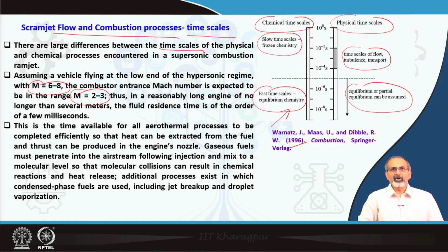Thus, in a reasonably long engine of no longer than several meters, the fluid residence time is of the order of a few milliseconds. Now, this is the time available for aerothermal processes to be completed efficiently, so that heat can be extracted from the fuel and thrust can be produced in the engine's nozzle. Gaseous fuels must penetrate into the airstream following injection and mix to a molecular level, so that the molecular collisions can result in chemical reactions and heat release.